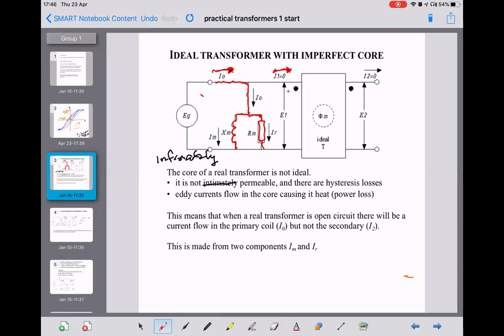And then the XM, the coil, the inductor, represents what's called the magnetizing current. So that's what current is required just to magnetize the primary winding, even though there's not a secondary load attached. Okay? So, how come the little m is used? What does the m signify?